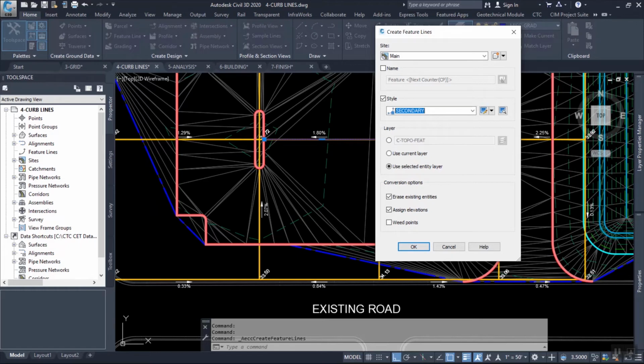They're going to go into the main site. So the only interaction we have with the setup surface and site is by making vertices relative to the surface. But don't put the feature lines in the same site. When you want to veer away from the setup surface for more detailed grading, it's going to get you in trouble. If you could absolutely stick with the setup surface, controlling every elevation, you could throw them in the same site, but I just don't think that's realistic.